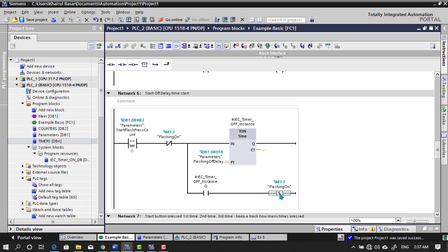In Siemens PLC, a range of M flags is retentive by default, and beyond that range, the M flags are non-retentive. Non-retentive means if you turn off the PLC, the bit status will be erased, so it will be 0 again.